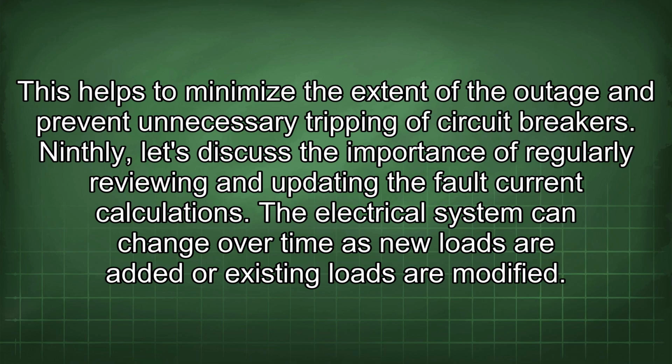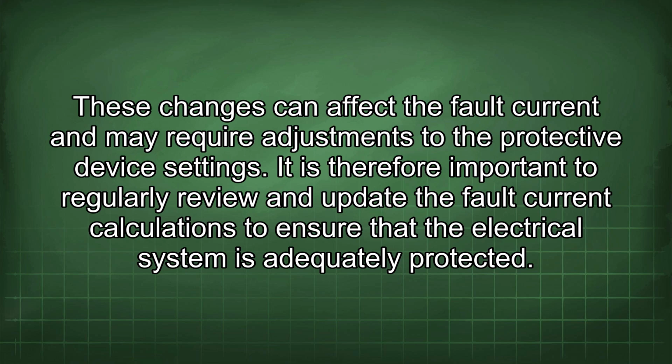Ninthly, let's discuss the importance of regularly reviewing and updating the fault current calculations. The electrical system can change over time as new loads are added or existing loads are modified. These changes can affect the fault current and may require adjustments to the protective device settings. It is therefore important to regularly review and update the fault current calculations to ensure that the electrical system is adequately protected.